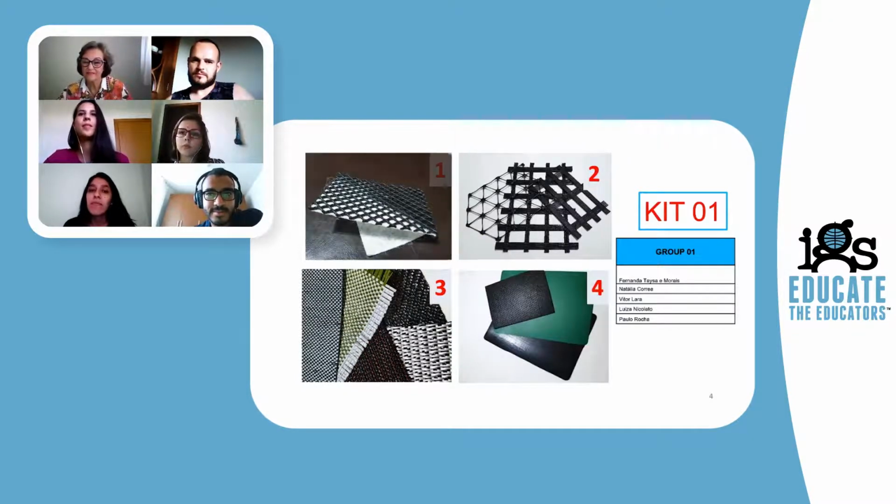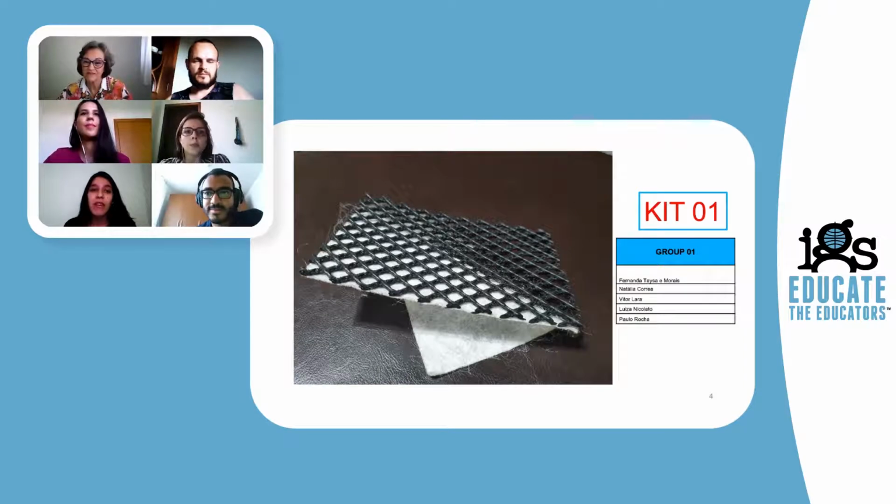What about number 1? I think number 1 is for drainage. Is it? Yes, I put drainage too. Geocomposite. Oh, it looks like a geonet and a non-woven geotextile. Right. Let me see here. I put the functions of drainage, filtration, and separation. What do you think?